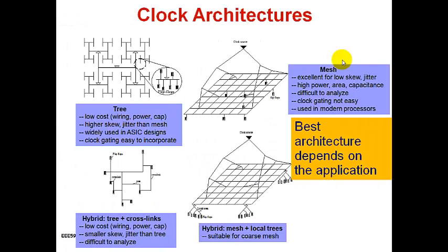The next, more different clock architectures you might have used, besides the H clock tree, is the mesh structure, with the clock source from which I take the clock in a mesh-like form to the different areas across the chip. The total chip area is supplied with the clock from here, around everywhere.